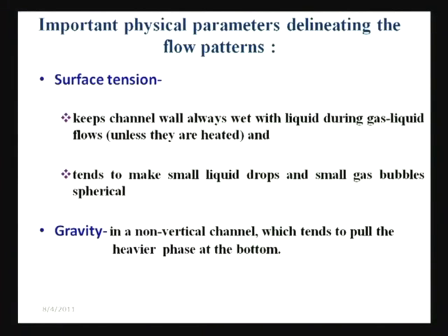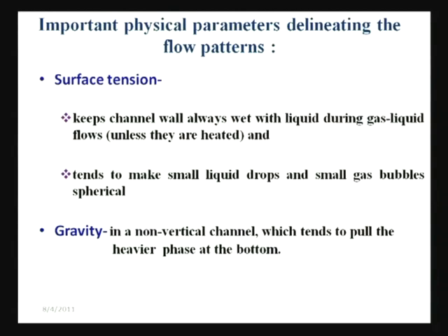Well, the other very important thing is gravity. Gravity in a non-vertical channel naturally tends to pull the heavier phase down and the lighter phase on the top. So, we will always have some sort of stratification where the lighter liquid or the lighter gas, whatever is the lighter phase, will be on the top and the heavier phase will be on the bottom. So, due to these two factors, more or less some order can be brought about in the apparently chaotic study of flow patterns which we feel.